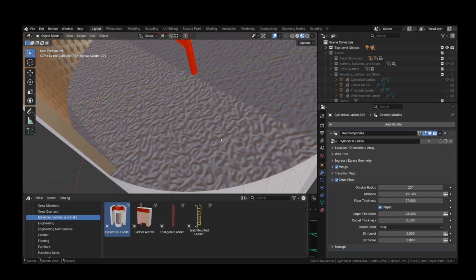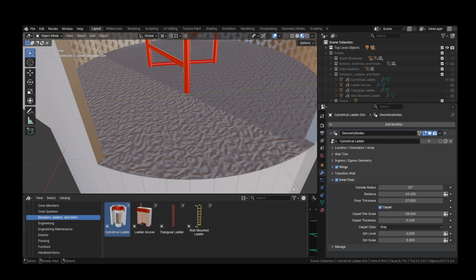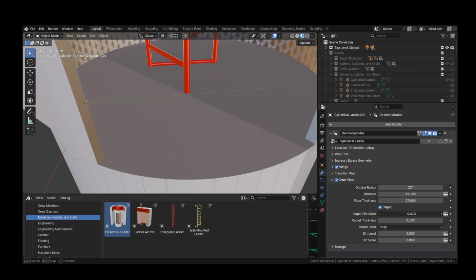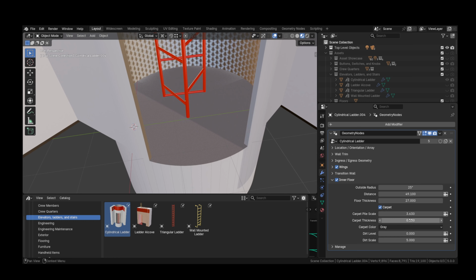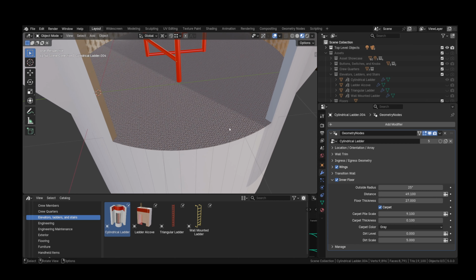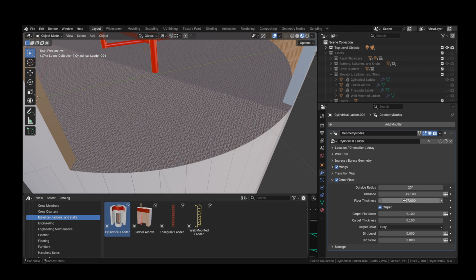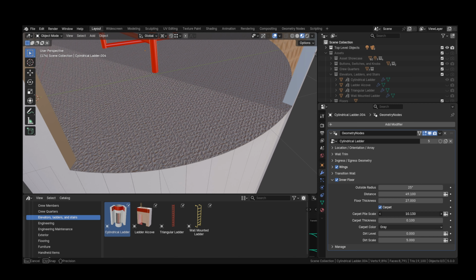But as you see, as I make that carpet bigger and bigger, the texture of the carpet gets larger and larger also. So with all of my carpet, I have this carpet pile scale setting where you can increase and decrease it to make it a very fine scale so that it looks appropriately carpety from a distance, to a larger scale. And this comes in when you're laying one piece of carpet asset next to another. You want those to be able to roughly match, so that's adjustable.